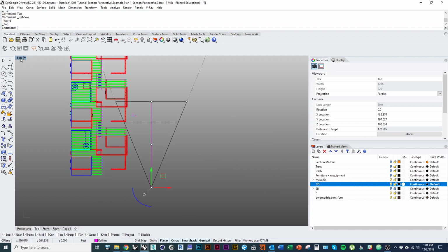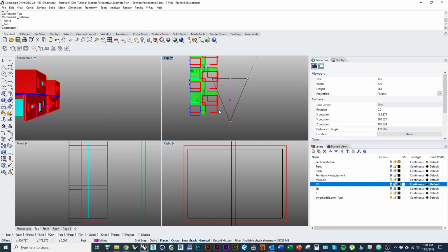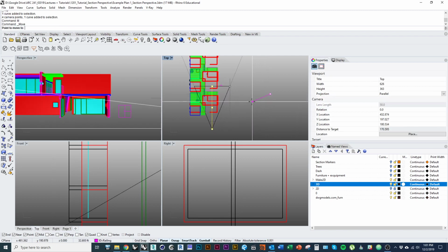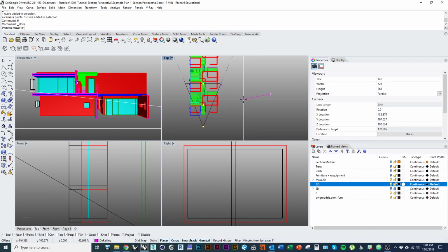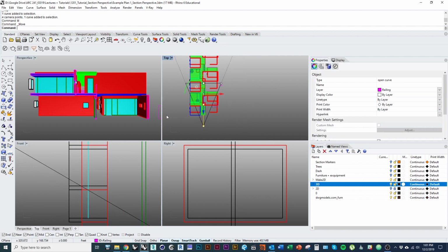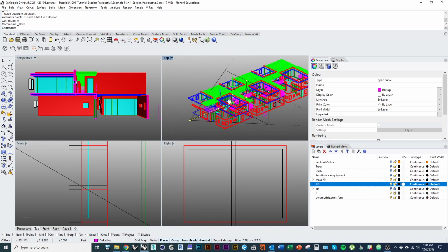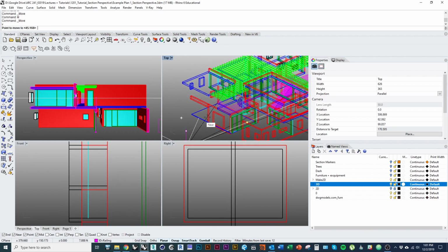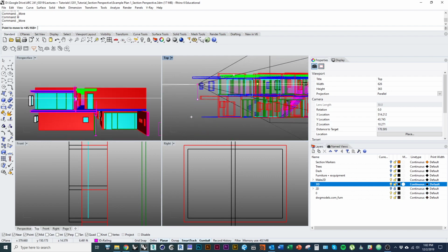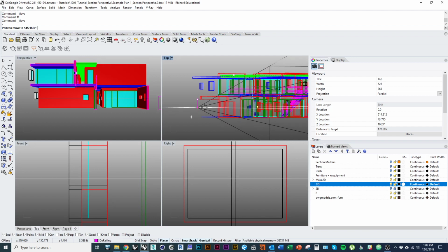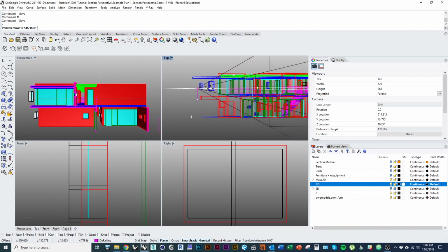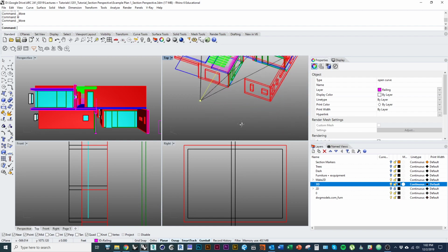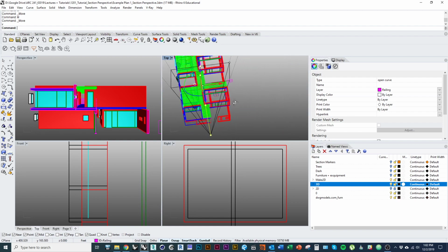So now all we need to do is move it into position. I'm going to go back to where I can see my perspective view. I'm going to grab that line and those 2 points there, and I'm just going to use the move command. Using my perspective view as a reference, I'm going to position it there. And what I would also like to do now is move it again. So I'm going to use the move command again, this time I'm going to hit vertical, and I'll snap to that start point. And what I want to do is basically choose an eye level perspective, either on the top floor or the bottom floor. I'm going to choose an eye level perspective on the top floor. I don't want to go too far. And you also may want to show.